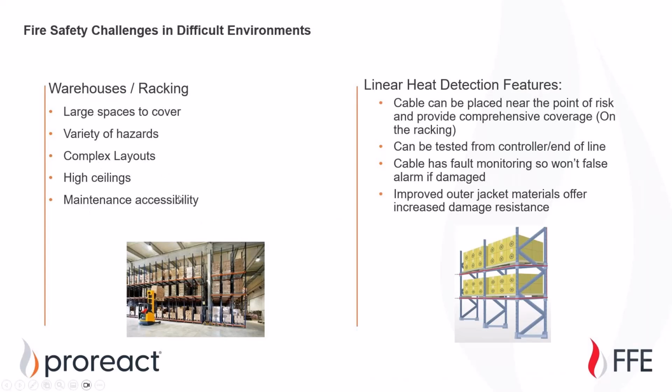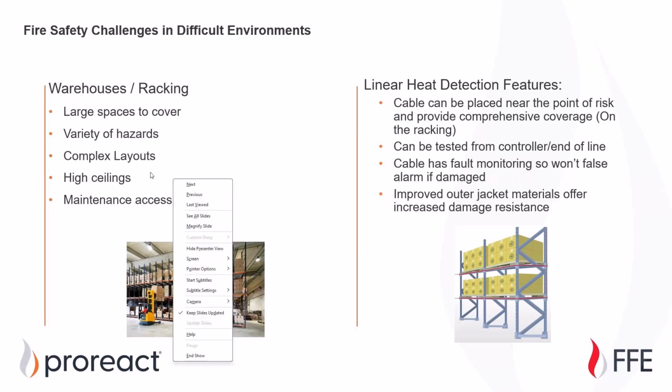So we did talk about warehouses and racking already. NFPA 13 is going to determine whether sprinklers are needed in a specific warehouse rack configuration. Linear heat detection could be used to release those lines prior to water flowing.